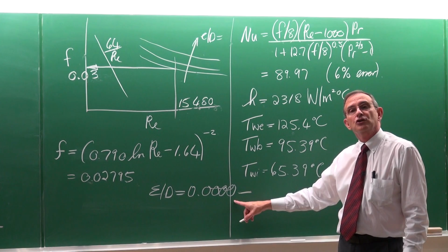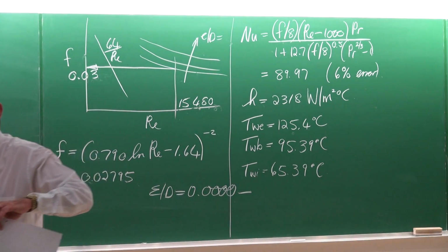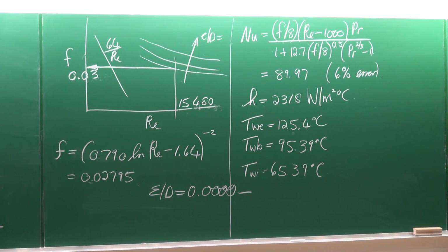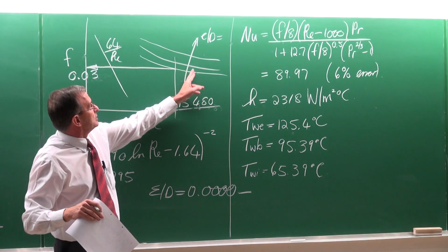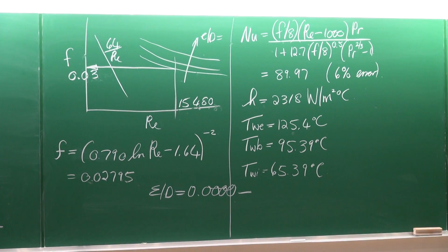In the old days, the tubes were cast, and they used sand on the inside. Those were actually at a stage called pipes and not tubes, because they were really rough. But these days it is almost impossible to get a rough tube. It's one of the experiments that we are busy with in our lab. We want to also do heat transfer coefficient experiments for rough tubes, and we find it very difficult to make the tubes rough.